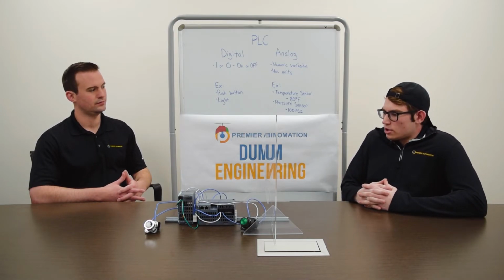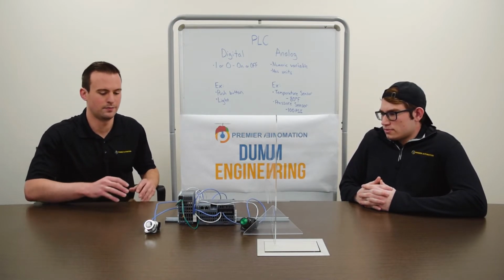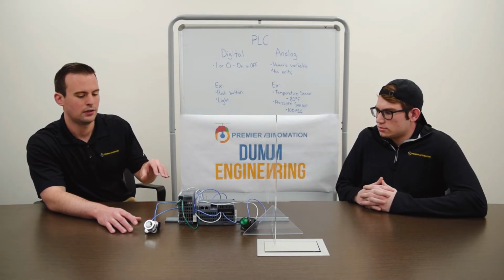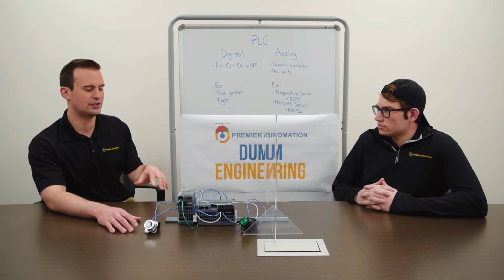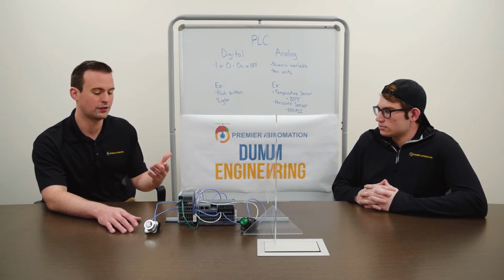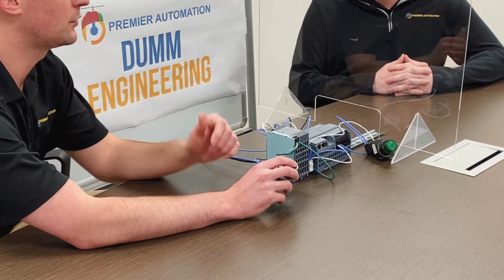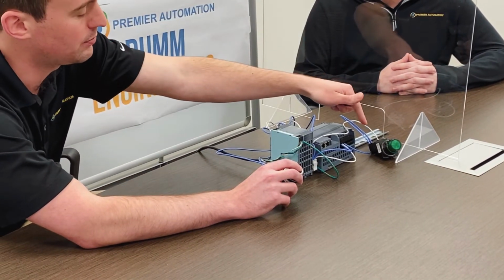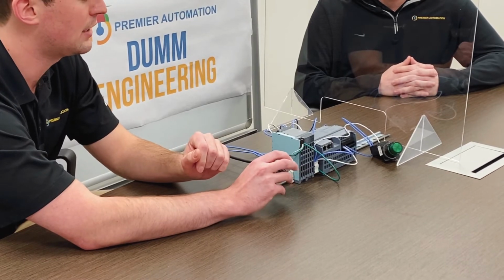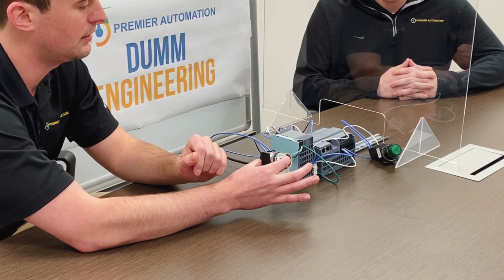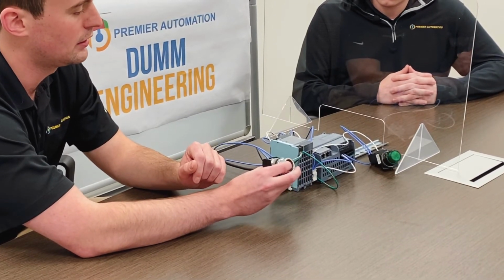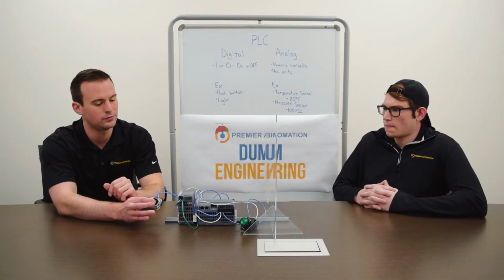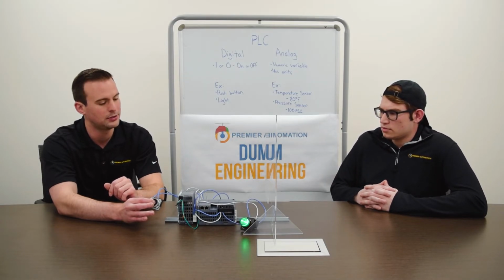Okay, cool. So I see you brought us a demo today. Want to explain how it works? Sure. Just to explain how a PLC can do more than just your standard turning on and off of a light. Like if we had a light switch, we would just be flicking it on and this light would be coming on. But instead we use some timers. When I press in the button and hold it for 4 seconds, then the LED comes on. So it's just a simple example of how you use a timer function in a PLC.